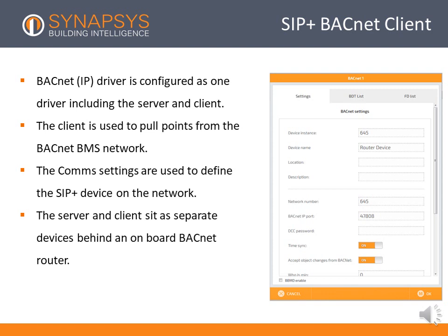The BACnet client device, as well as the BACnet servers that will be looked at later, sit as virtual BACnet devices on a virtual BACnet network. The BACnet client sits behind the router using a unique network number.